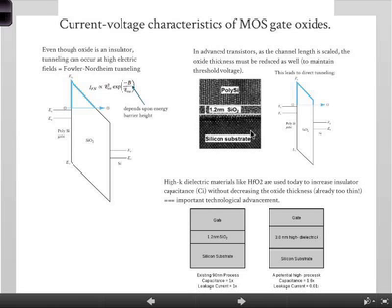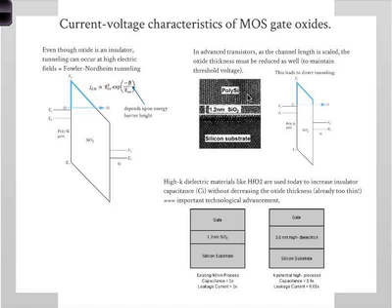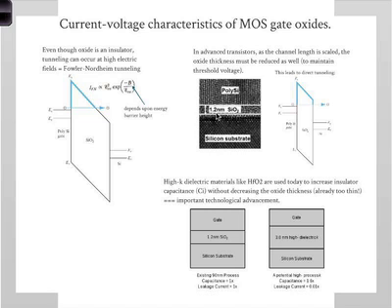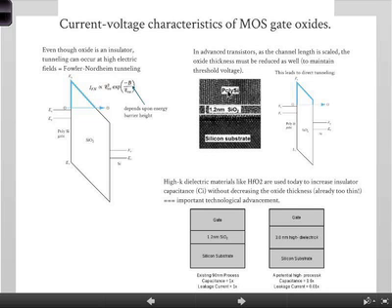Okay? So this is a transmission electron micrograph of an advanced transistor, where of course you have a silicon substrate. This is our body. Okay, channel is formed right there, and you have an oxide. And look at that, 1.2 nanometers. That's about 10 to 20 atoms of silicon. Pretty small. Okay, and then you have polysilicon. In fact, if you look carefully, you can see the atomic electronic wave functions actually. Okay? So it's pretty incredible that you can actually see it.